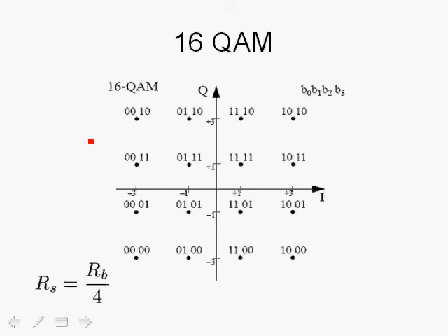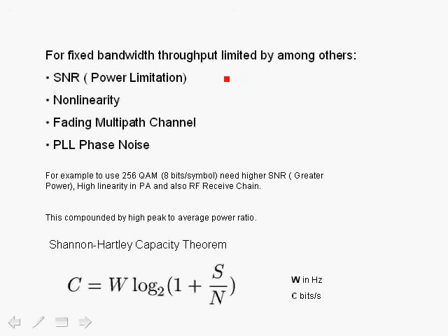Now since the symbols are then modulated and sent over the channel, we can theoretically achieve high throughput, high bit rates by using more and more points in the constellation. And this is a key method by which we can achieve high throughput or high bit rates over band limited channels: to map the bits into more and more points in the constellation. For example, in OFDM 802.11a, we use 64-point QAM in addition to 16 QAM. So if we have a fixed bandwidth, we can actually increase the throughput by mapping bits to points in a constellation and then modulating these symbols in the constellation.